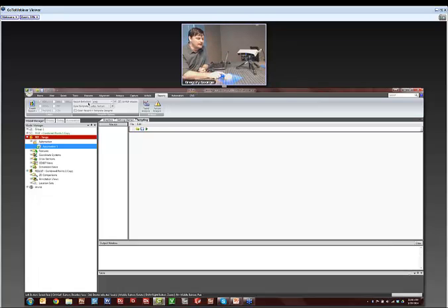I mean, you can put the stickers all over the part, but right now we don't support a separate photogrammetry feature where we could take a large overall shot of the targets and then take individual shots of the part. So the technique that we're using now is to put the stickers on, and they would have to be overlapping shots that include at least 3 of the stickers, if not more, to increase accuracy. Overlapping shots to go all the way around.